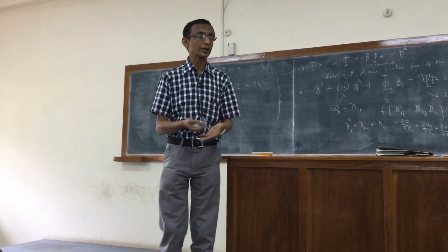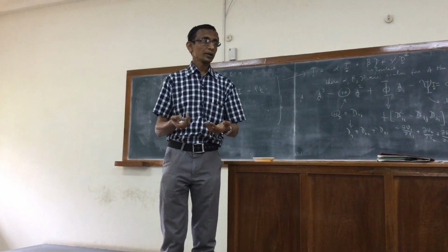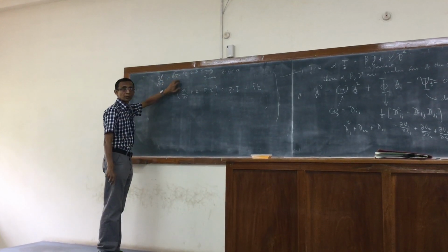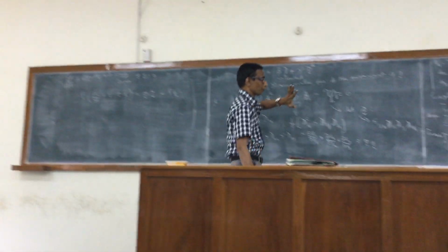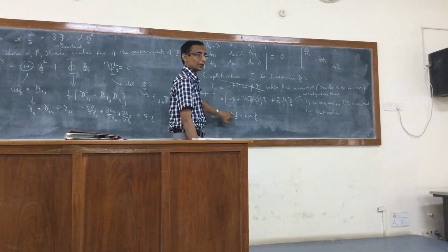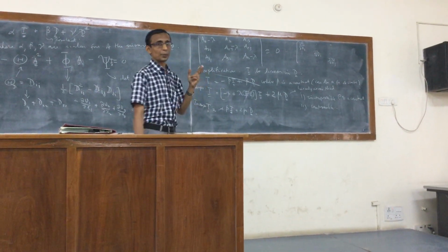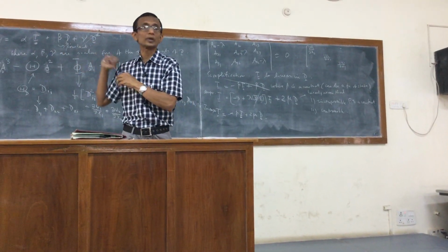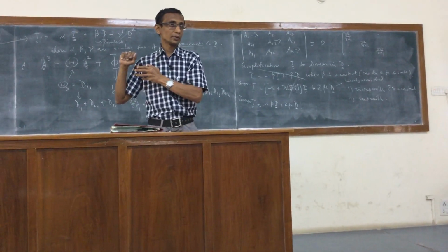It's no longer to be determined by the equations of continuity and motion. So then we seem to have 4 equations but only 3 variables. However, it's important to remember that the pressure is no longer a thermodynamic variable, which it is for the compressible fluid. That's the important difference. So the pressure now becomes a mechanical variable to be determined from the equations of motion.